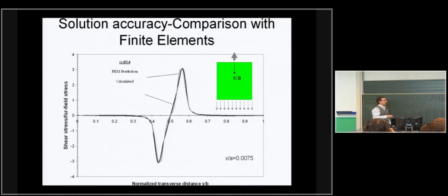So as far as the reinforcement in the transfer along the y coordinate, we would only need to reinforce the center of the plate, which you would expect because the point load is at the center. Then you would need to reinforce the center. The question is, though, how far on either side of the center should that reinforcement go?